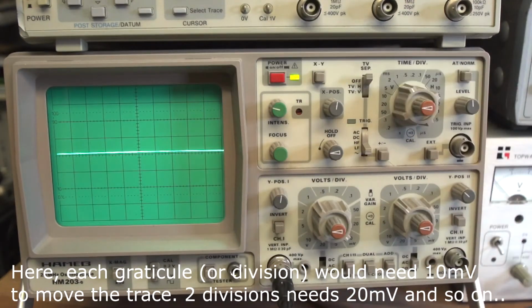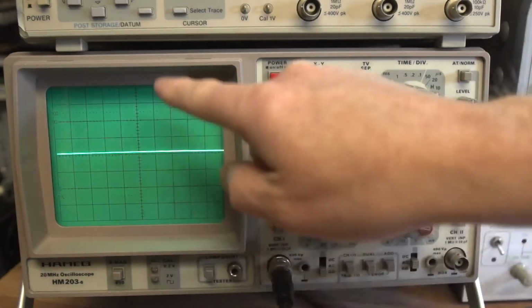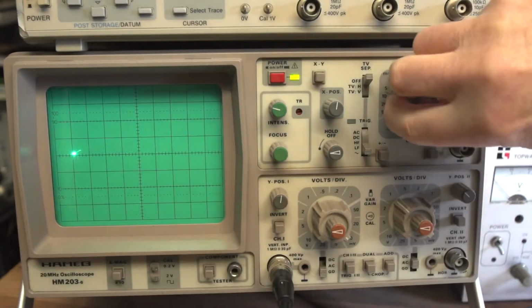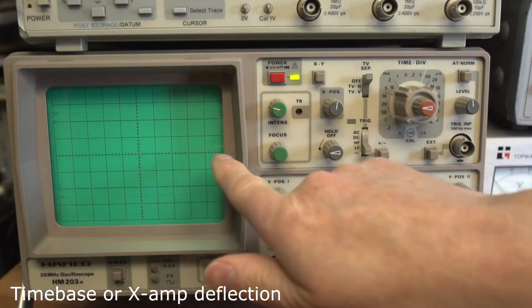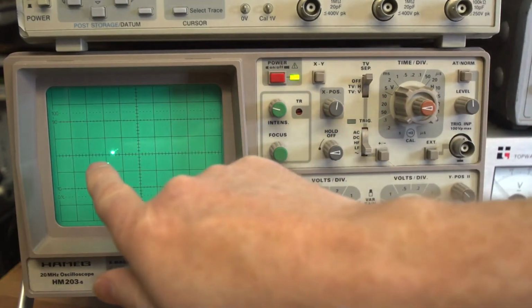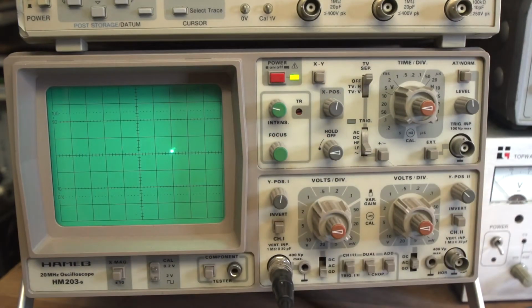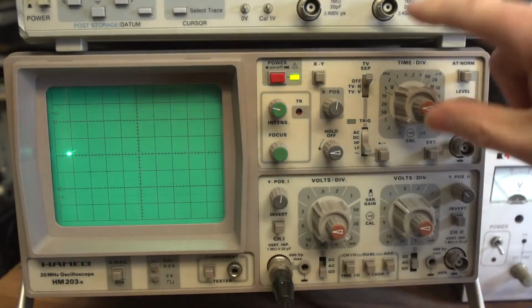So that's your Y deflection. You have Y, which is, if you like, up and down, or amplitude. And you have X, which is being shown right now. And if I slow the time base down, you'll see it as a moving dot. That's the time base moving the X deflection as a function of time. So it takes a certain amount of time to cross the screen. It's actually 0.2 of a second. That's 200 milliseconds per graticule, per 1 centimeter square. So it takes 200 milliseconds to get across each one of those squares when it's set in this position.